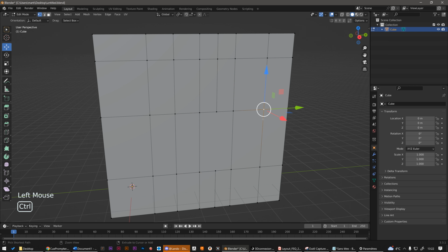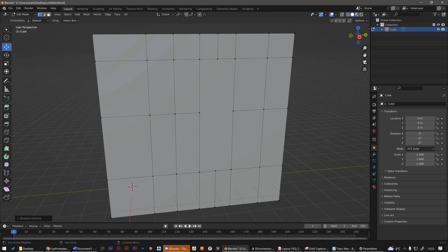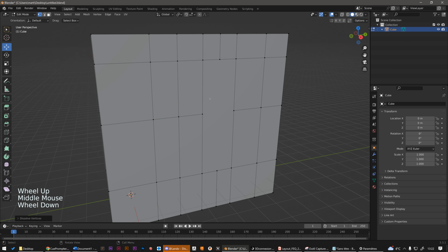We can also dissolve vertices. So, I undo again what we did. I select that vertex, press the X key, and dissolve the vertex. Here's what it gives us. This time all edges which the vertex was belonging to have been dissolved, and so the 4 faces which the edges were belonging to have been merged into an 8 vertices n-gon. Here I'm showing you how to dissolve without any specific purpose.